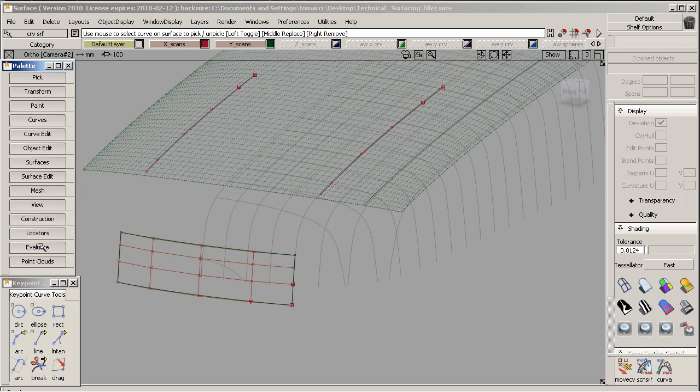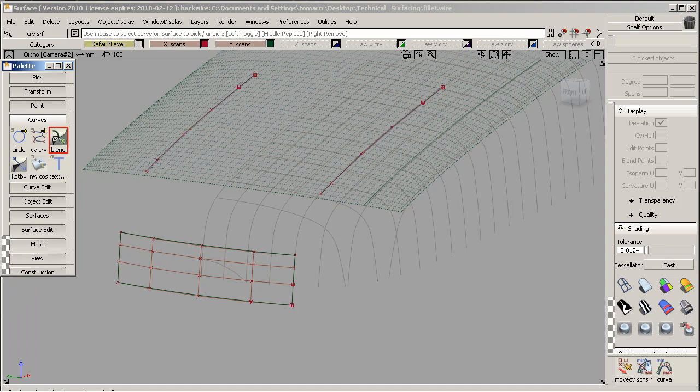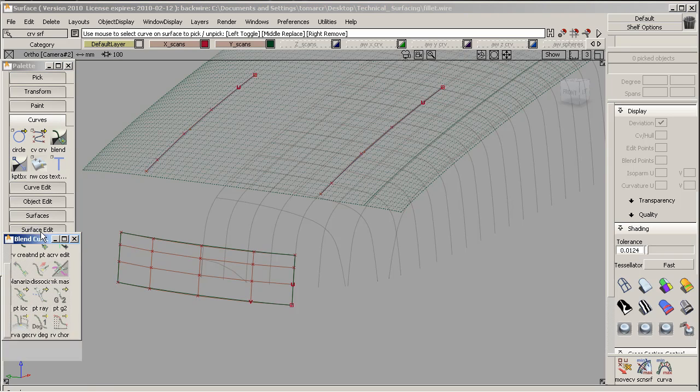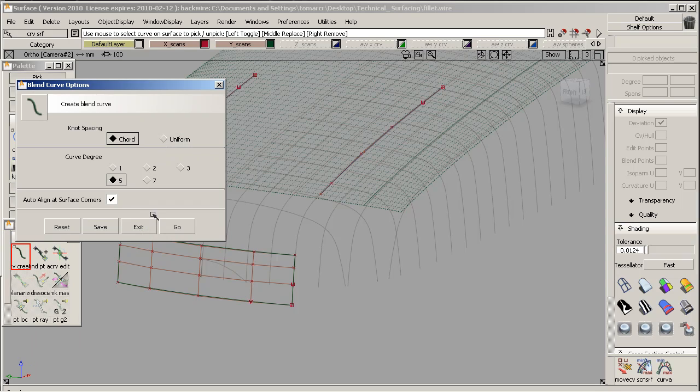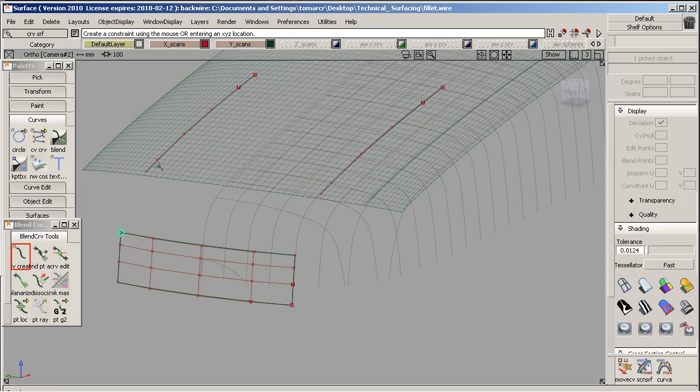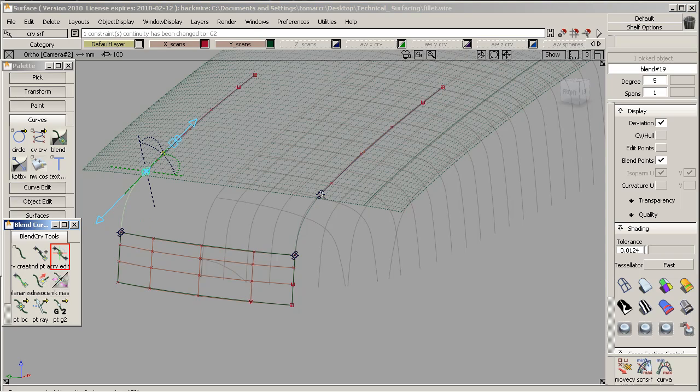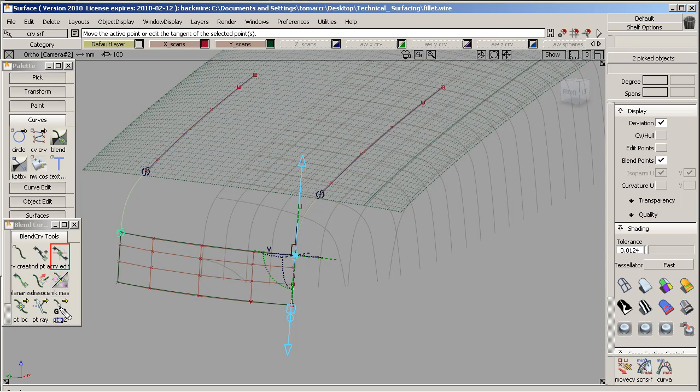And now we're ready to create our curves using a blend. Okay, we want to make sure we have this option on, and pick the rebuild curve. Okay, we're going to align these. We want G2, and there as well. And if I actually shift and pick both, I can do both at the same time.